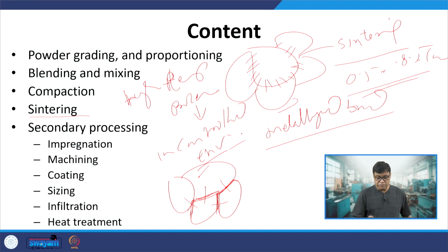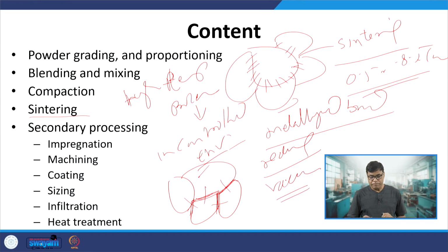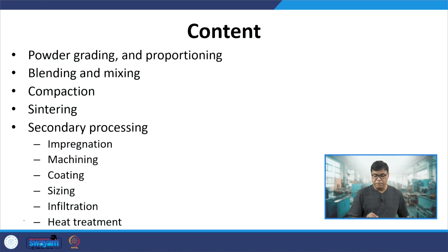Therefore, it is important that the heating for the sintering is done in a controlled environment, which can be a reducing environment or it can be vacuum as per the need, so that when the green briquette is heated to the higher temperature, no impurities or oxide layers are formed between the powder particles which are being sintered to develop the desired mechanical properties.